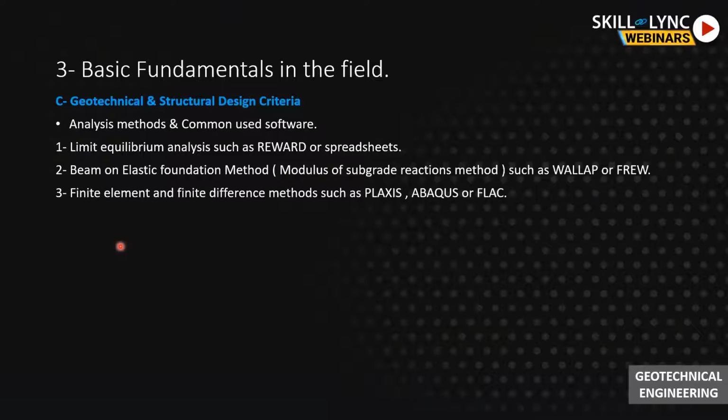For the finite element method, we can use Plaxis or Abaqus or FLAC, any software commercially available for your company. But the finite element method has a lot of features, like you can model complicated shoring designs if we have two-step walls and we have existing buildings. So in finite element method, we can check everything. We can check the displacement outside the shoring wall. We can do seepage analysis. So it's very important software, and it will be useful and easy for the engineers to use.